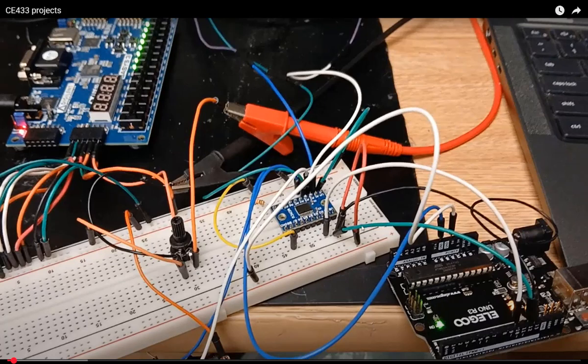And that's it. So there are basically only 3 pins, right? SCK, SS, and MISO. So it's the same on the other side. SCK, SS, and MISO. I forgot the order, but the first one is SCK, I think the second one is MISO, and the third one was SS. It doesn't really matter. You just have to connect B5 to A5 accordingly. If B5 is MISO, A5 should be MISO, right? Because it's like one channel from a higher voltage to a lower voltage.